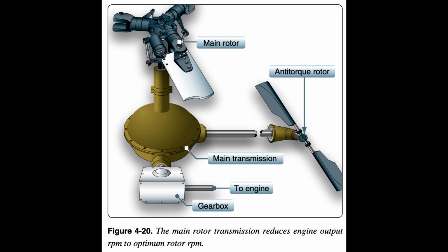On reciprocating and fixed turbine engines, a clutch is required to enable engine start. Air or windmilling starts are not possible. The two main types of clutches are the centrifugal clutch and the idler or manual clutch. How the clutch engages the main rotor system during engine start differs between helicopter designs.